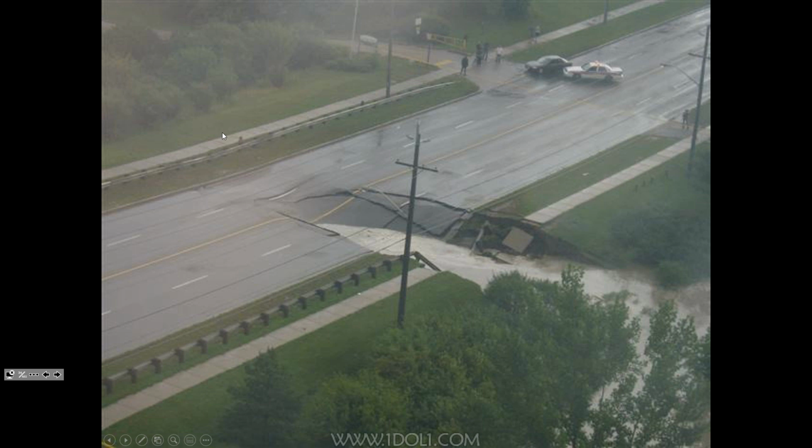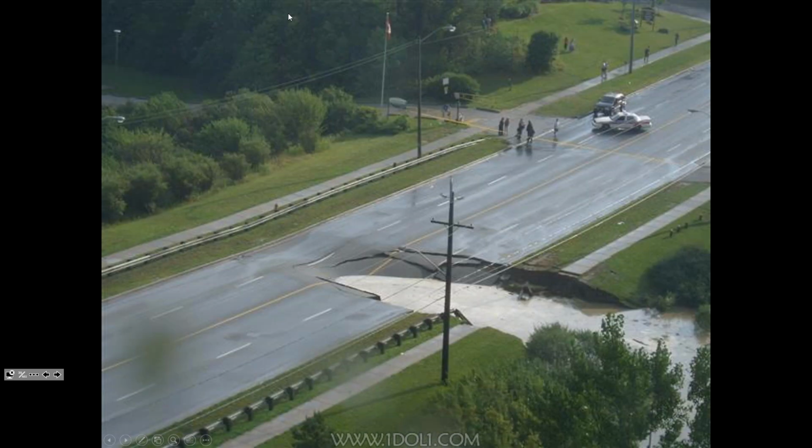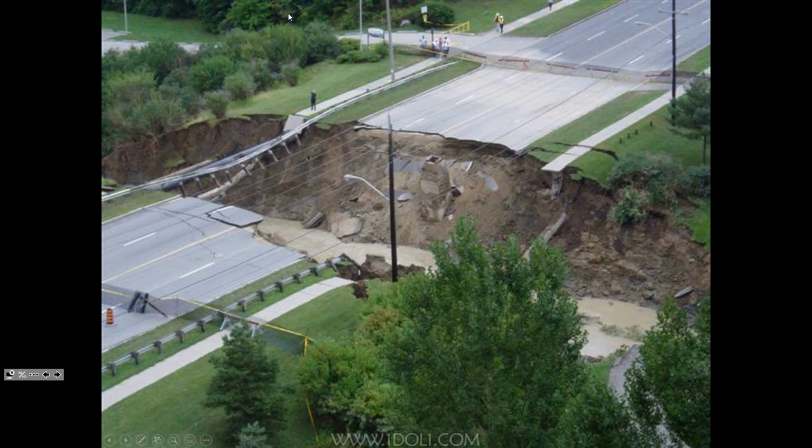And it caused something called piping, which is where the small grain particles of soil get pushed out, and then the water starts to flow a little bit faster and faster until finally soil around the outside of the culvert has been scoured, and it causes a lot of damage. You can see that this road is closed for a good long time, and it's in part because the culvert that was supposed to carry this water was undersized, and there was too much head wall pressure pushing the water around the soil rather than through the culvert.